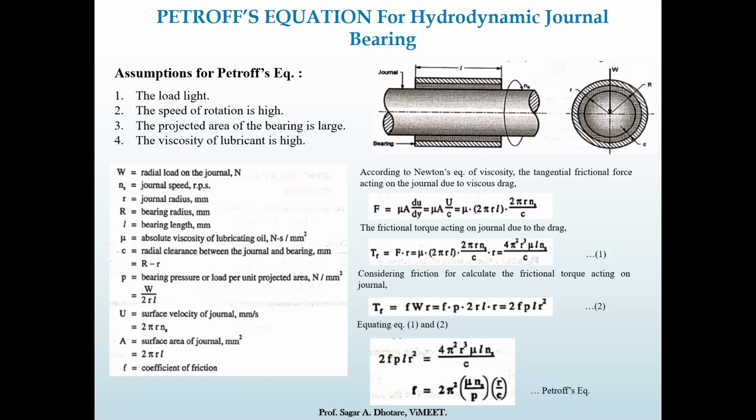And last, the viscosity of the lubricant should be high. If it is not, then it is very difficult to separate them and to generate a high hydrodynamic action.